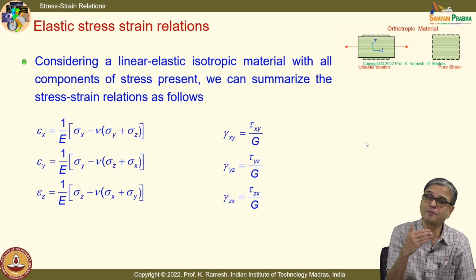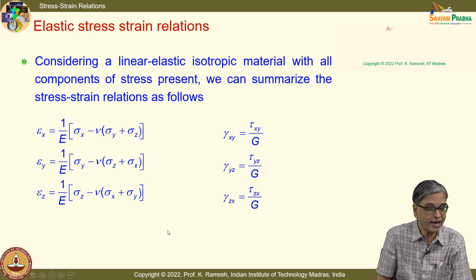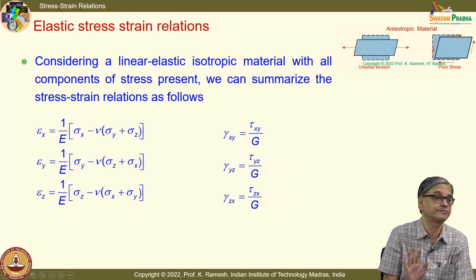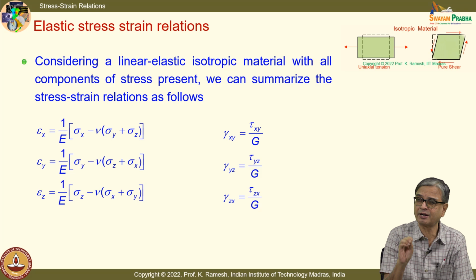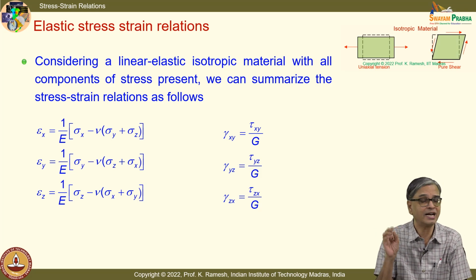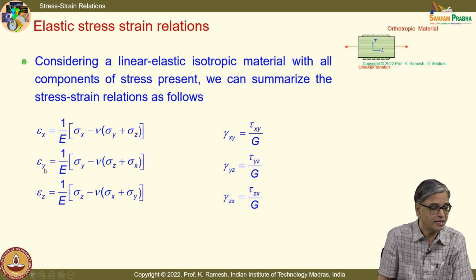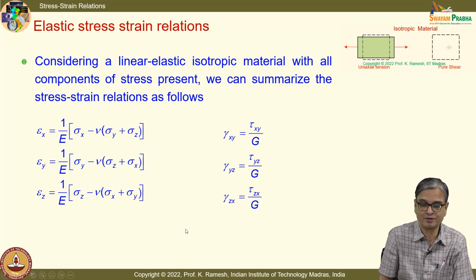You are in a position to model it comfortably, and whenever you write the stress strain relations, you should write them completely and knock off the terms that are 0. Do not say, from your tension test, epsilon yy equal to sigma yy divided by Young's modulus. That is applicable only for a tension test. In a generic situation, epsilon yy is related to 1 by E times (sigma y minus nu times (sigma z plus sigma x)). Nu is multiplied to sigma z as well as sigma x; similarly for the other components, sigma y as well as sigma z, sigma x as well as sigma y.